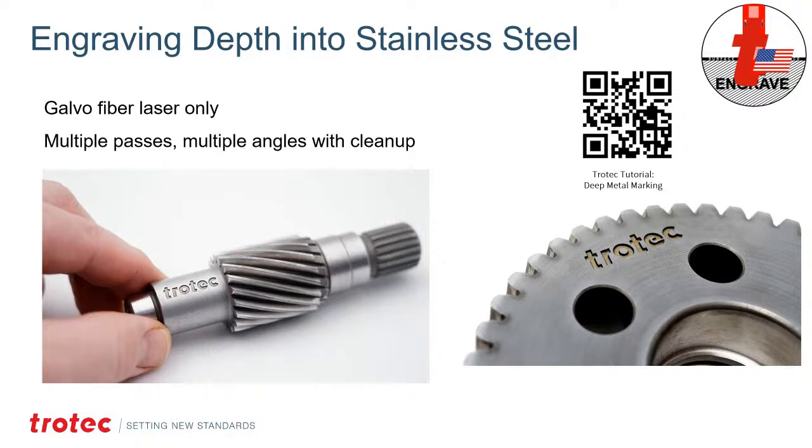And I have a tutorial here. If you are interested in this, you can scan this QR code and it'll explain from start to finish, using our SpeedMarker software all the way through our Galvo system, how to create depth with a Galvo fiber laser. The benefit is that it can go multiple passes, 10, 20, 30, 40, 50 passes, depending on the depth that you want. So it can be time consuming, and the total time will depend on what wattage of laser you have. Just like CO2, fiber lasers have wattages ranging all the way up, and the higher the wattage you can afford, the faster, of course, it's going to produce depth.